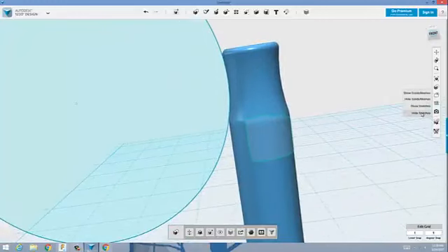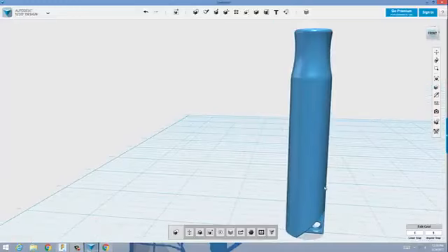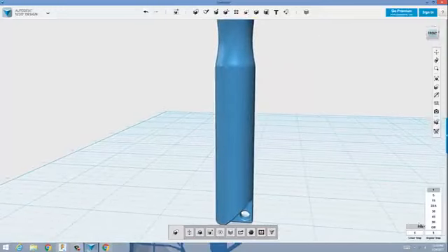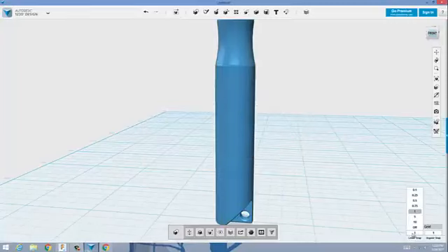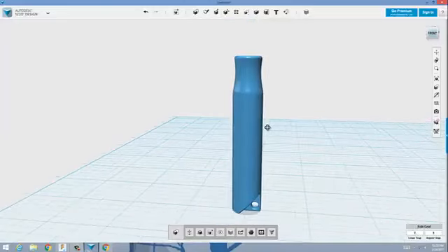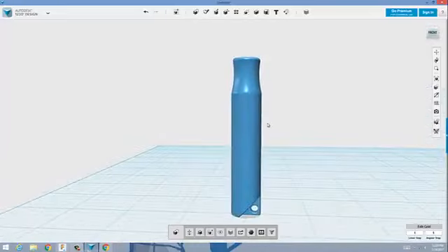I'm going to hide all of my sketches, and I've now brought you to the point where you have to figure out the rest. What you're going to do is carve out a little angular piece here inside your whistle so the air blows past all of that. Keep in mind that I'm using millimeters on my grid right here. That's going to be helpful for the dimensions that I've given you. And I've left the linear snap to 1 millimeter. And there's the whistle. Now you figure out how to finish it out. Good luck.